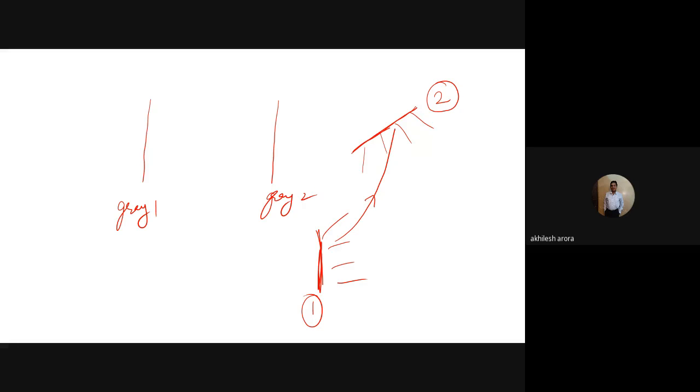Because of their orientation, we have to introduce one more factor, and this factor is actually known as the shape factor. Because of different shapes, means because of the different orientations or the way the bodies are put, the energy which is leaving body one may not be in totality reaching body two, and this is taken care of with the help of the shape factor. So finally we can say that Q net, which is exchanged between two gray bodies, is given by sigma into A into Fg into F epsilon into T1 raised to power 4 minus T2 raised to power 4.